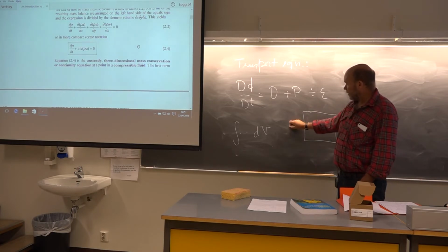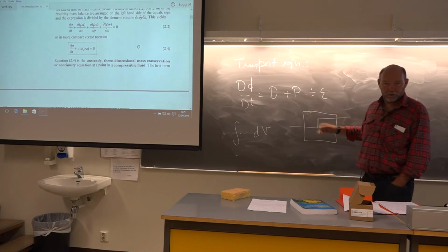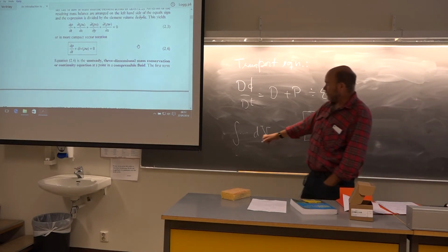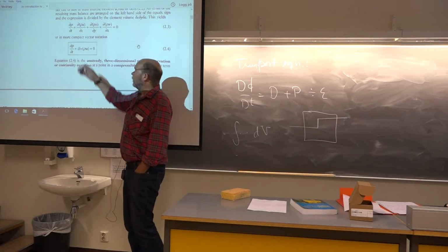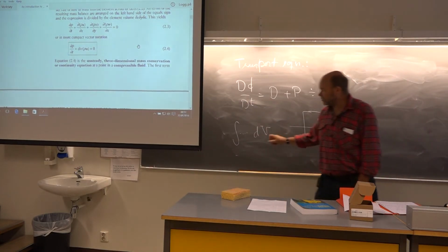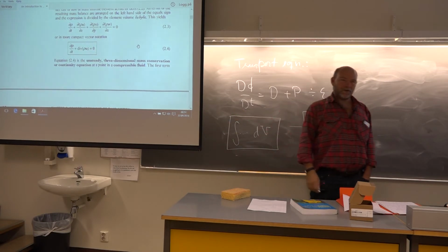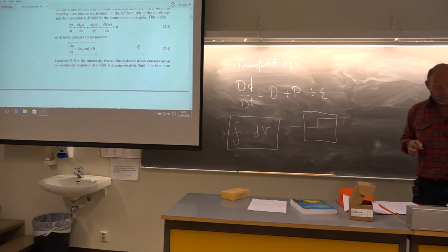Then you can have a velocity or density that all of a sudden makes a jump, like you would in a shock. And that's quite okay in an integral formulation, but it's not valid with a differential equation. So my point is, if you are using finite volume, start with your basic equations in the integral form. It covers more physics, so start directly with it.